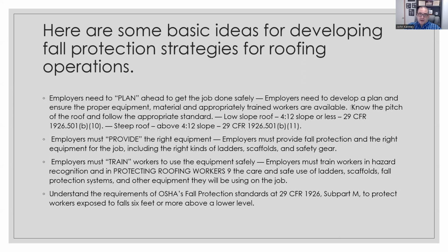And I always recommend everybody signs off at the end of this to make sure they understand the training that they've just gone through. Understanding the requirements of OSHA fall protection standards to protect your workers exposed to falls 6 feet or more above a lower level. So again, you want to have these trainings in how this fall protection works. And you, as the employer, must understand this in order to get that training out to your workers.